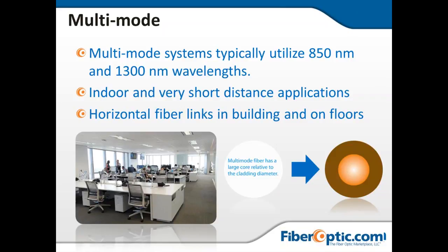You don't need like a 40 dB OTDR for multimode. You'll never shoot that far. You'll never have multimode that travels that far because from the industry specifications, it's really meant to be at a maximum of like 2 kilometers, and even at that, it's really expecting like 10 megabits per second transmission rate. So you're looking at maybe fire suppression systems, signaling systems, for signs or something like that. Very, very low bandwidth applications.